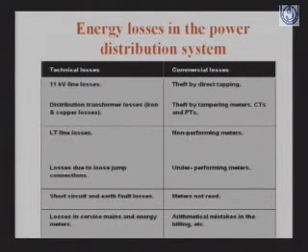And commercial losses are theft by direct tapping. Many of us might have noticed such things in day-to-day experience. Then theft by tampering with meters, CTs and PTs, which changes the ratio, non-performing or underperforming meters, meters not read properly, and mathematical mistakes in the billing.